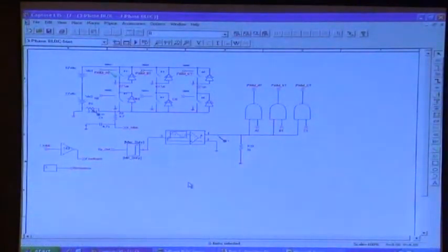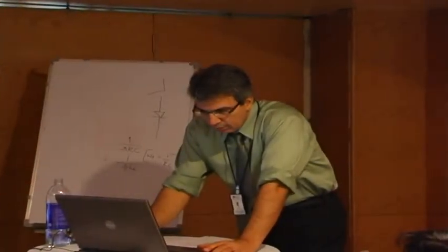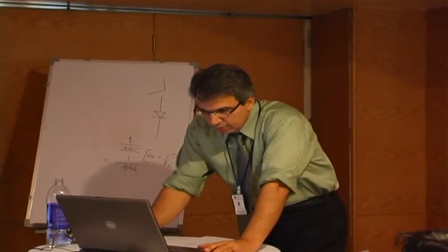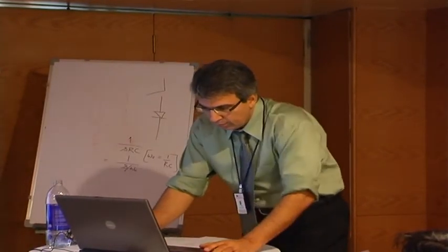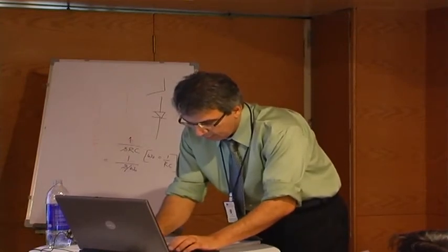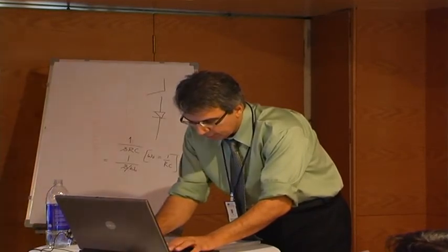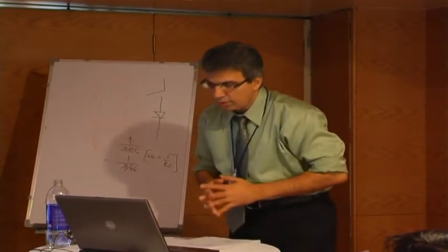So, and then we can also look at the currents. So let's see here. We can open up a new window, and I can add IL1, which is the motor inductance. That's your motor current.